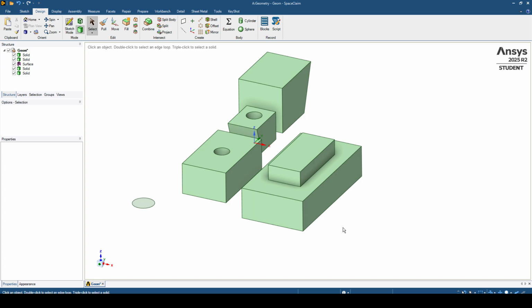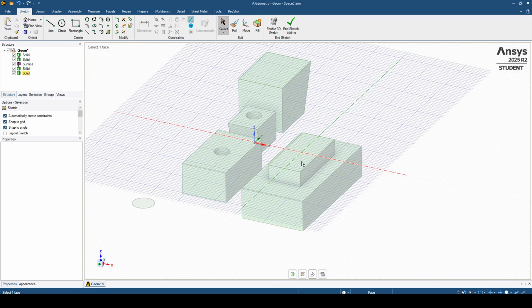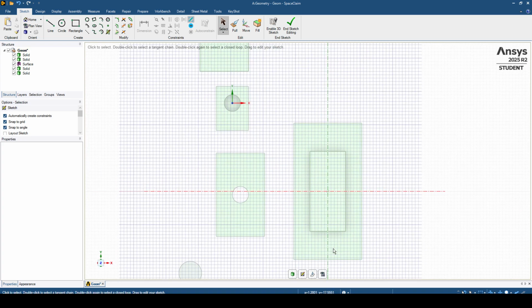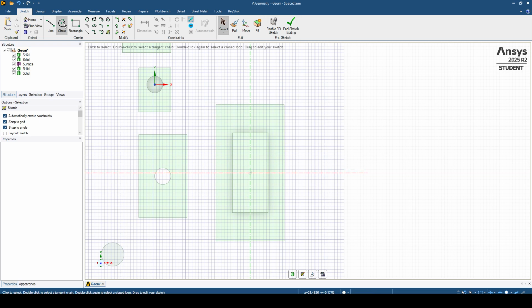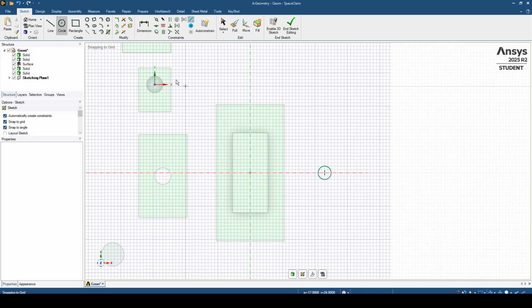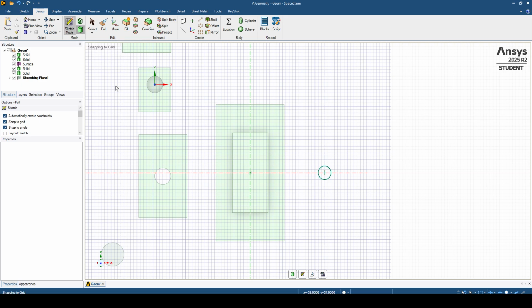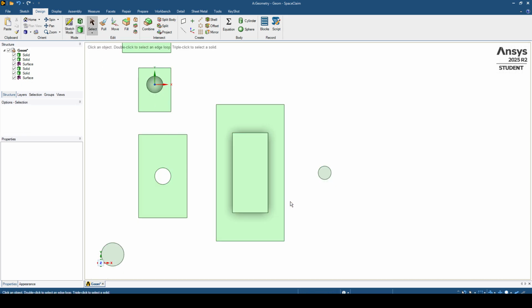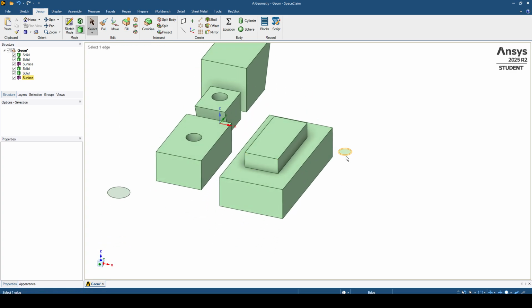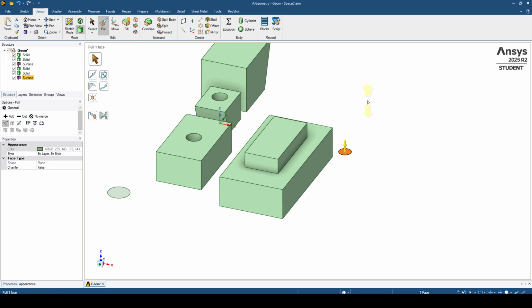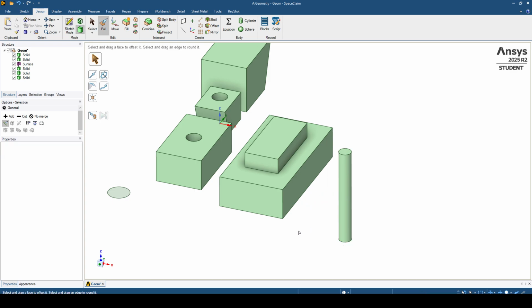Now let's try to do the subtract or cut shapes through the Boolean operations. Let's sketch on the top of this face. We go to the plan view. I will sketch outside, for example, a circular form, which is small. For example, I will give 4 millimeter as a diameter. I will exit the sketch mode now and rotate the view. We can pull this face downward. Let's do it long enough. Let's do it 30 millimeter, and we can exit now.